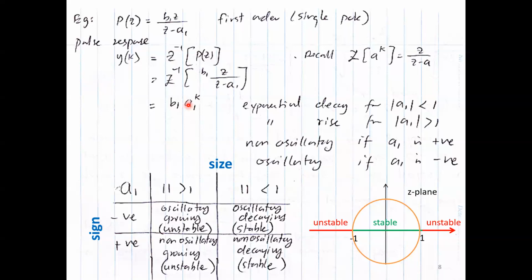Remember that. A lot of people think the other way, like if you have a system, when you discretize, you have a unique model, right? It's not very correct to understand it that way. You don't get a unique model in discrete time when you discretize a continuous plant. Your model in discrete time very much depends on the sampling interval you chose, or any other modification that you introduced in the process.